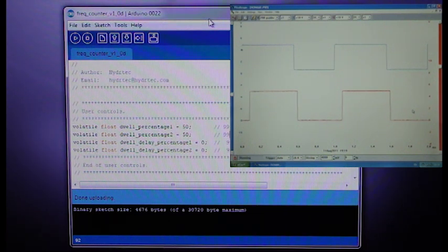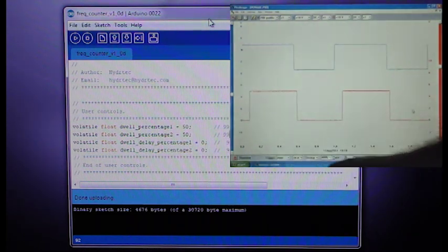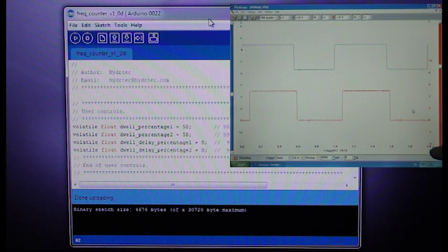But before we do that, I just want to establish one or two things. The DSO is currently set to 200 microseconds per division, therefore showing from the left to the right edges of the screen 2 milliseconds. So roughly we're getting 1 pulse per millisecond. I'm just going to set it so that it's roughly a 50% duty cycle, and as I do that you'll notice that the output pulse characteristics are not affected by the duty cycle settings of the input pulses.